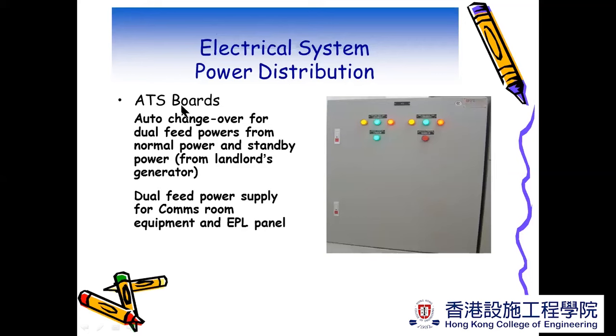And the ATS, we mentioned about the ATS. The ATS is a device which is called the automatic transfer switch, which selects the normal power in all cases. But as time goes on, when the normal power breaks down, it will switch to the essential supply right away. And normally, the ATS would take the alternative source of supply, either by the supply company or by the genset.